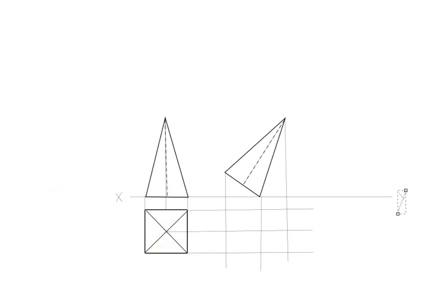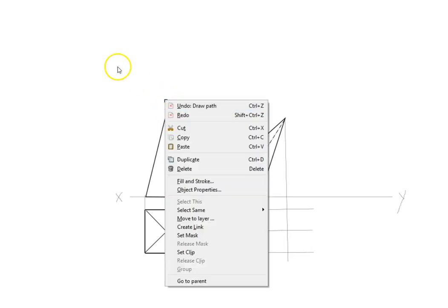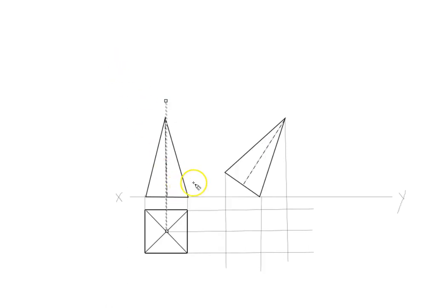The next step would be to project all the corners, starting with the axis first, straight up above the XY line like that. Then we mark the axis height as given from the XY line to the required height.